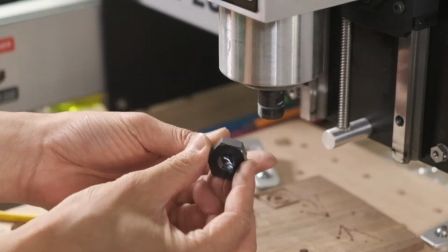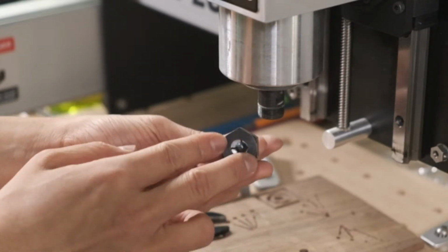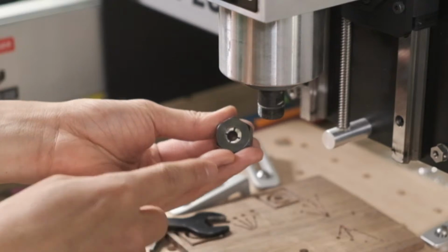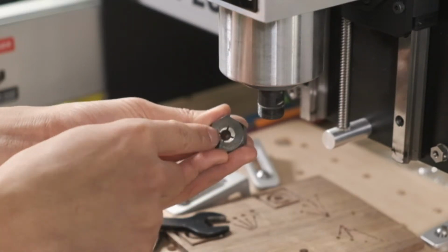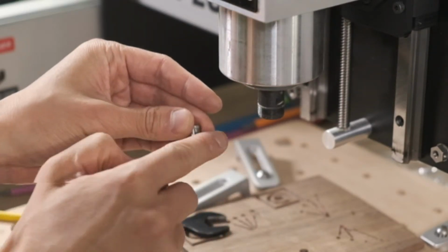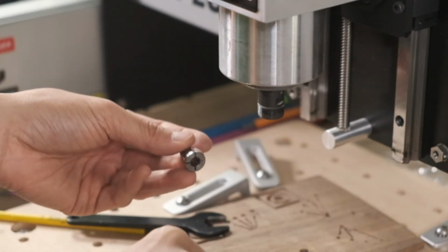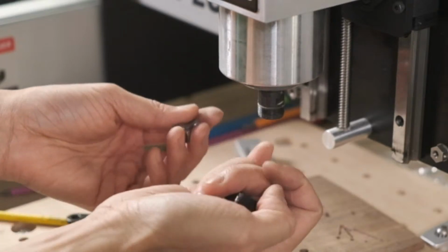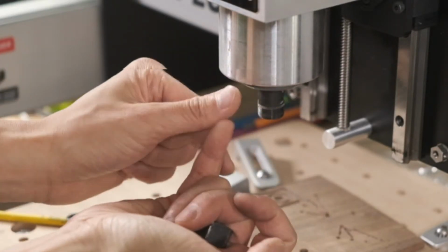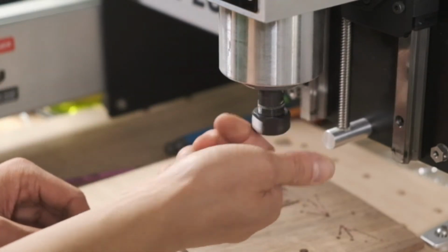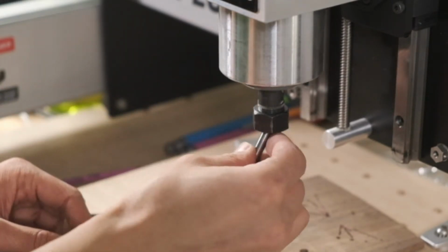So even if you are still using a 1/4 inch collet, but you're changing tools, when you pull out the tool, there's usually a ring of dust in there, and if there's dust in there, there's probably dust everywhere else on there too. So I would just loosen the collet, give that a little tap, shake it out, give it a little quick wipe down, make sure there's no residue, and then reload everything. So that is my collet cleaning regimen.